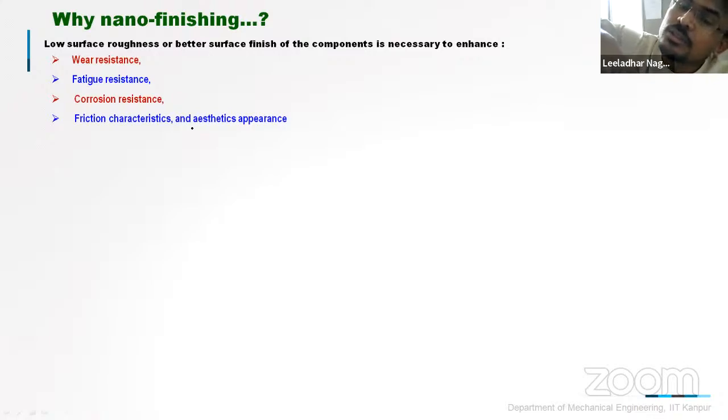That's why we are using stainless steel and titanium alloy, which are biocompatible materials with load carrying capacity. Suppose I need it for the spinal joints, then based on that we select the particular joints for the application. It will depend on how much load that joint is carrying. The second thing is that it should be a biocompatible material. Biocompatibility is very important in this case.